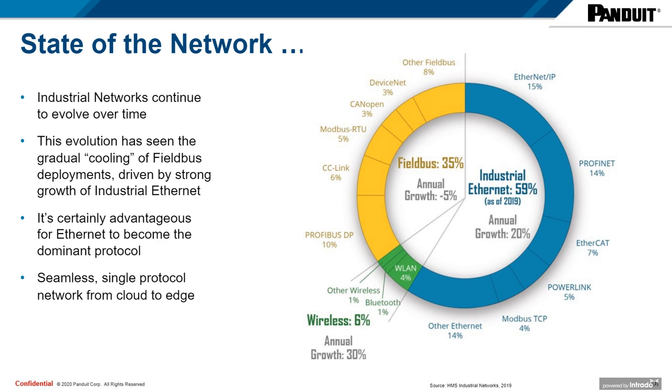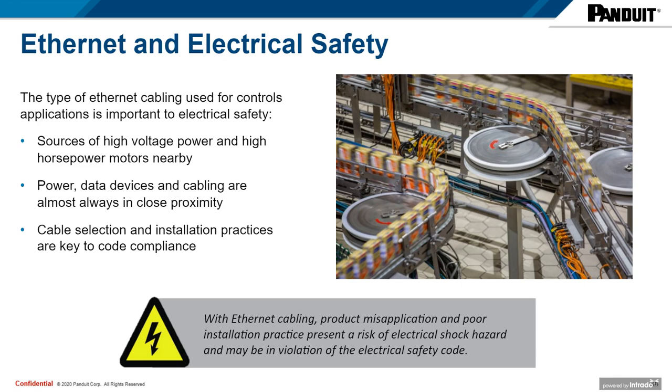So the presence of Ethernet devices and those industrial managed network switches is increasing and becoming very common in the control panels today. In fact, multiple devices within a control panel is very common. So you're starting to have to plan better for how those Ethernet cables are routed. Because Ethernet is so widely available, misapplication of the Ethernet cabling happens frequently.